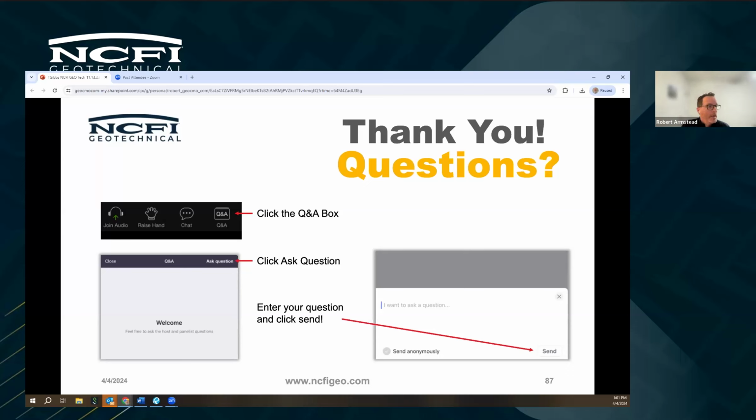All right, I'm going to continue on. Can the product be used to create a waterproof curtain beneath the concrete foundation to prevent water intrusion into a basement? Yes, if the soils are correct for it. If there's a gravel base underneath that slab or sandy loose soils, the single component could be injected to create a mat essentially underneath the slab. But it does need to be the right soil type.